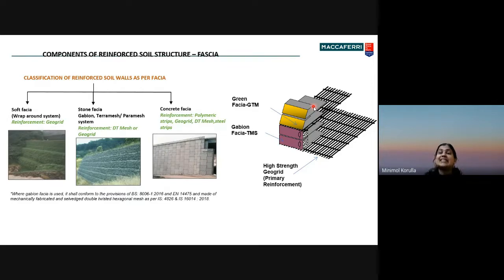So it is a woven mesh, which is the same mesh of gabions or mattresses, and inside that a weld mesh will be placed. Why weld mesh? Because the woven mesh has flexibility and will not retain the shape. If we place a welded mesh inside that, then the woven mesh can stand. And apart from that, one more material will be added, that is coir geotextile.